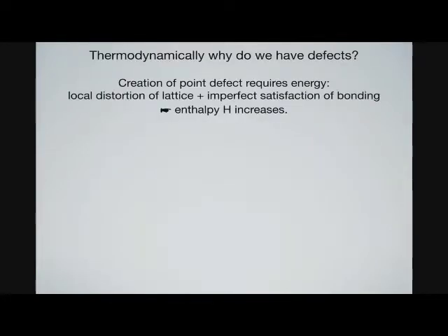What does that have to do now with the reason for defects, right? So thermodynamically, why do we have defects? We have those two state functions, enthalpy and entropy. And if we think about taking that perfect crystal lattice and we take an atom out, we rip one out of an equilibrium position, that certainly requires energy, right?